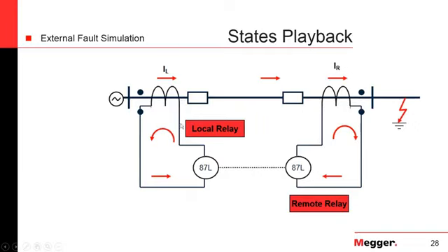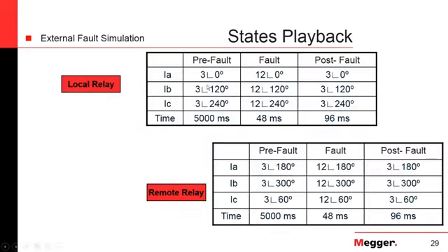What you do is you determine what the voltages and the currents are in both ends of the line for 3 different states. In one state, you will call it the pre-fault state, and by pre-fault you mean a state in which you have steady state conditions, you don't have a fault, you have something going on in the system that could go on forever and nobody has to care about that.